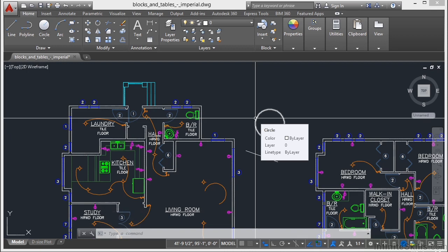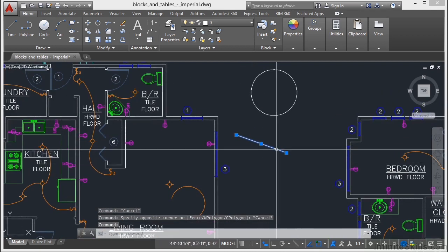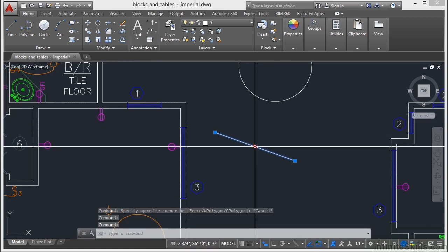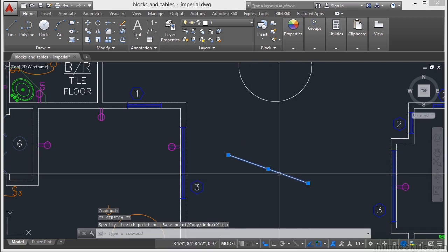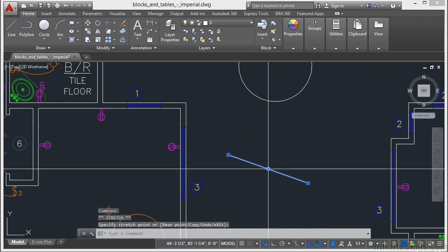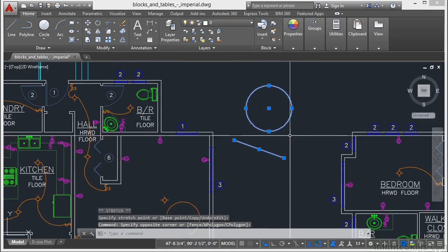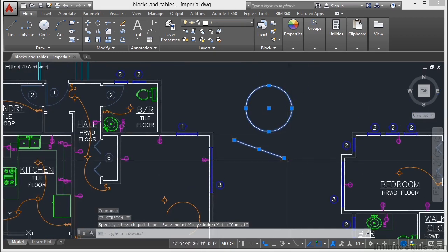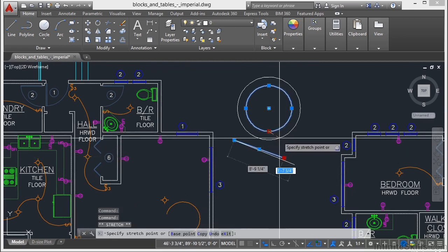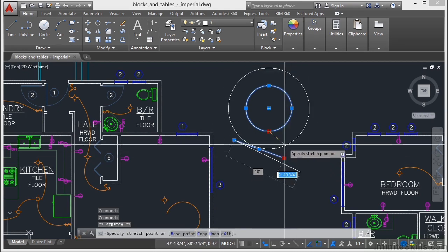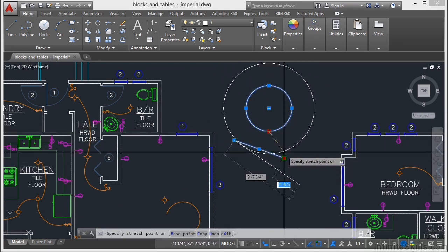Now, you can select multiple grips at a time. So if I select this line, select the midpoint and the endpoint, this becomes a move command, and it's going to keep these relative to each other. It's kind of like still doing just the center point. But if I select another object and I select by holding down Shift, just that one grip, as well as that grip, I'm changing both of them relative to each other. So I'm changing them both according to how I move it.